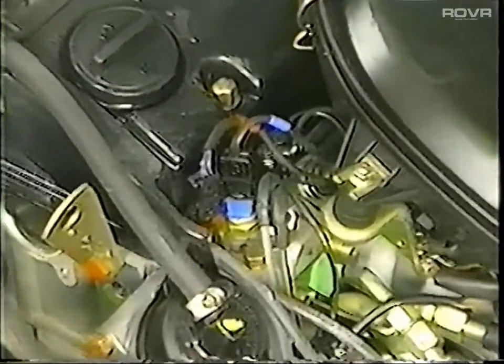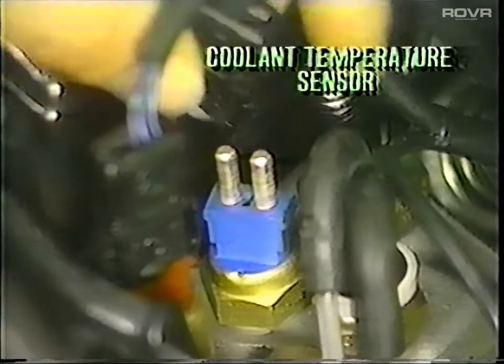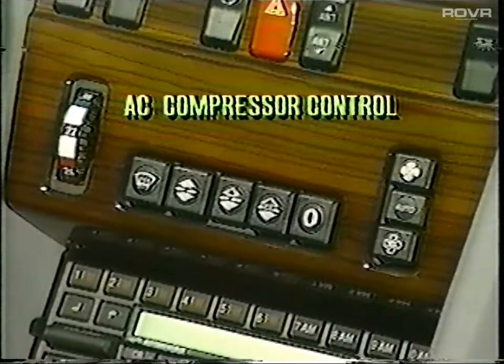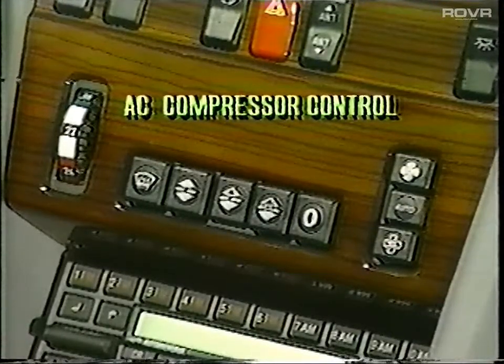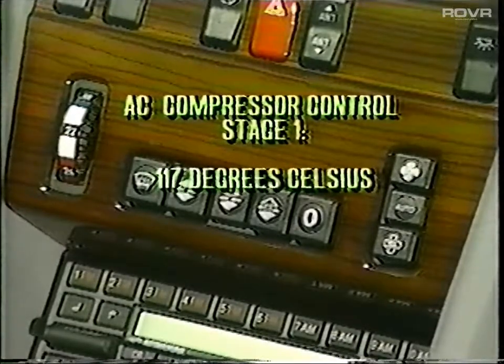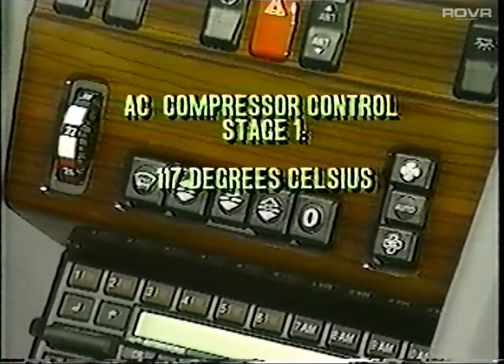The AC compressor shut-off is now controlled by a coolant temperature sensor instead of the previous temperature switch. Also, to prevent engine overheating, the AC compressor will now shut off in 2 stages. At a coolant temperature of 117 degrees Celsius, the running time of the compressor will be reduced by 50%.